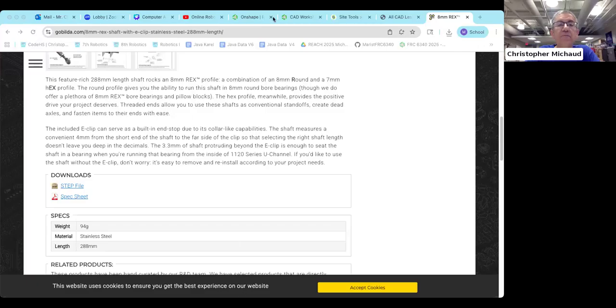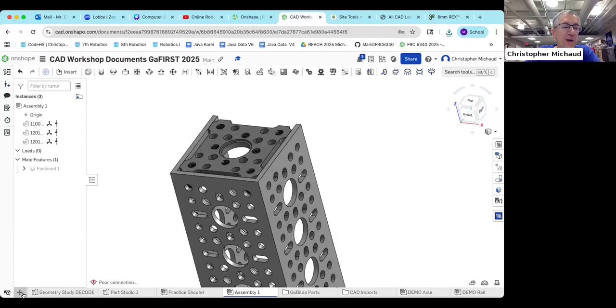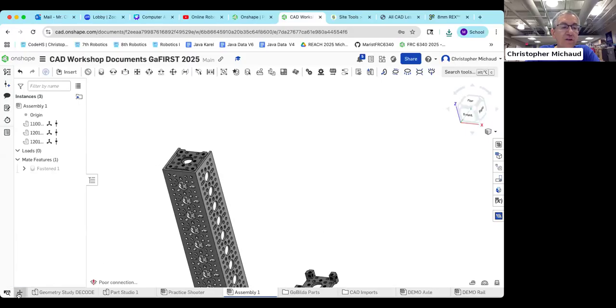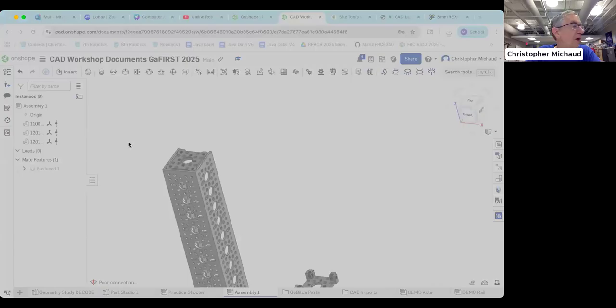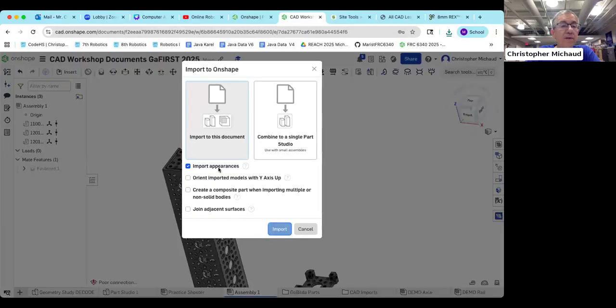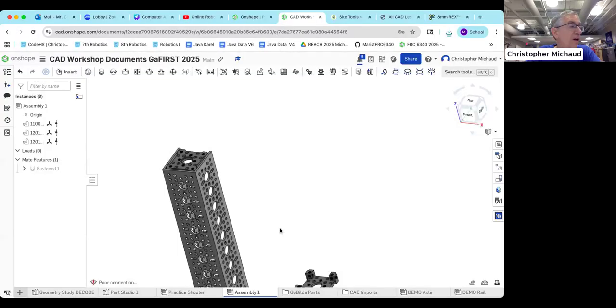Then once you extract it, which I know you didn't see, go back to OnShape. You can use import. Then you go to your downloads, which my system dialogues come up, and you guys can't see that, but I'm going to go to downloads, and if I select the file 216, I can import it, and then it will take the time. It talks about importing it. I'm just going to click import, and then it will work on bringing in the part.